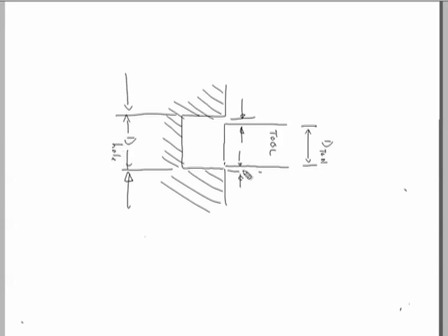It should be one diameter each side of the abrasive particle. This is abrasive and this is abrasive, so this is the average abrasive diameter. So that the abrasives can enter and, after doing the work or cutting here, can come out through this. This is basically followed while designing a tool in case of USM.